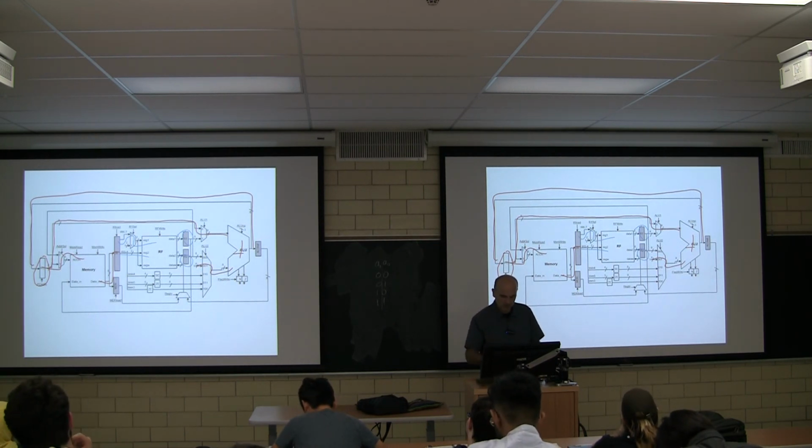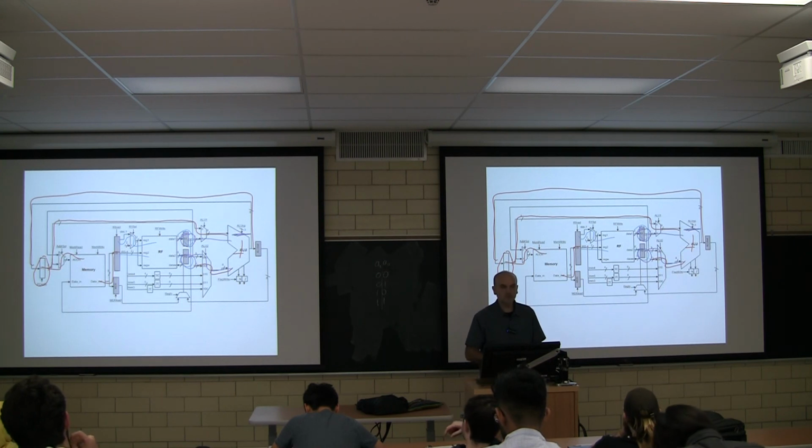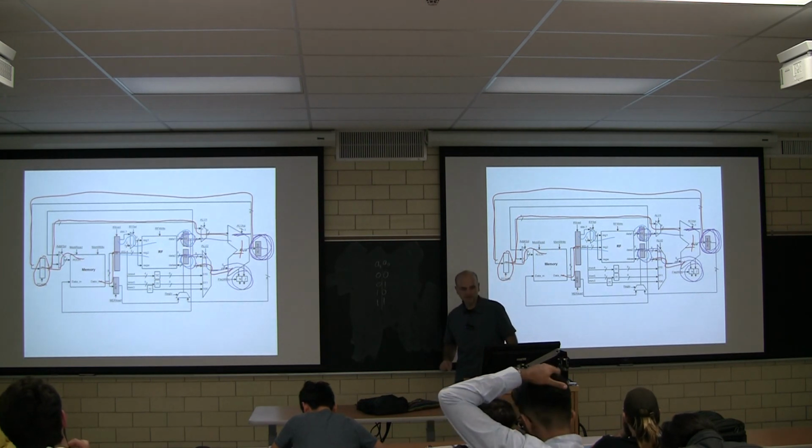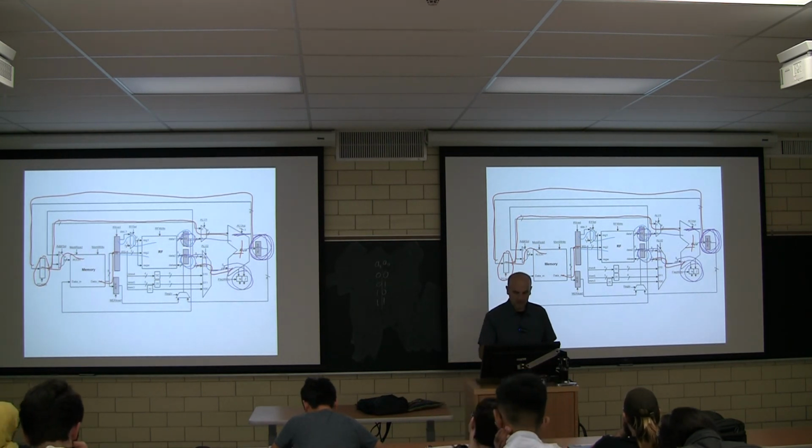Color, magenta. Magenta looks nice. Cycle 3. We take these guys now, pass them as operands to the ALU. We're doing subtract because this is what we want. And at the end of cycle 3, we update this guy and this. This is cycle 3. Finally, in cycle 4, we're going to send the results back to the register file.